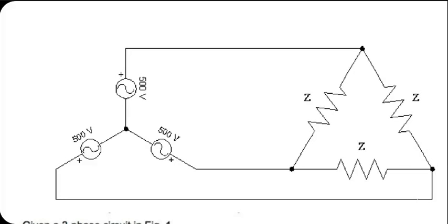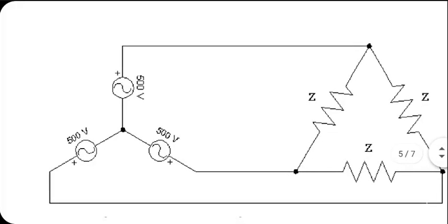That ground wire, because we know it for sure will have zero potential no matter how unbalanced the power system has become, that zero potential can be used as a reference for diagnostic purposes and for measurement purposes. So don't confuse ground wire in power systems with neutral wire in the power system. Neutral wire is simply coming out from the common node. Ground wire is actually grounded in the ground, or somehow we make sure it is at zero potential all the time.